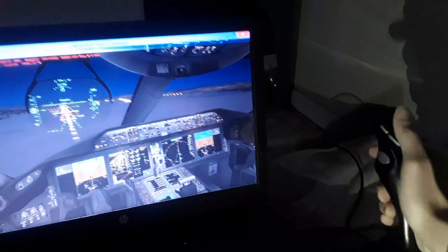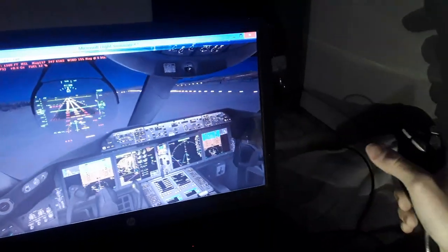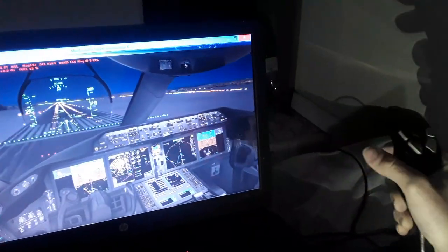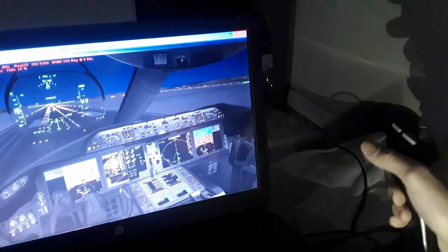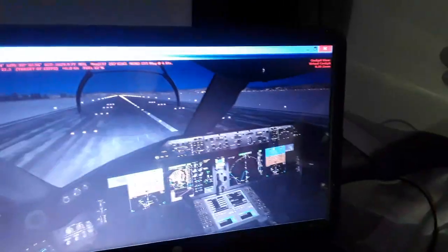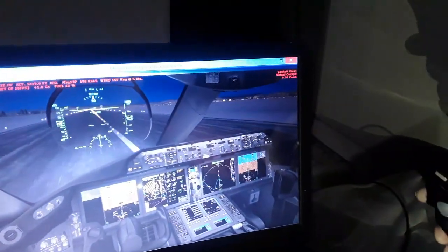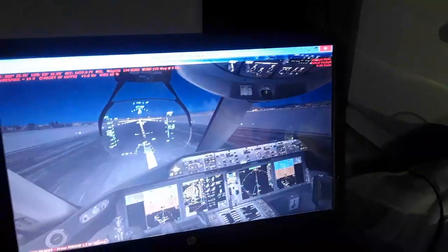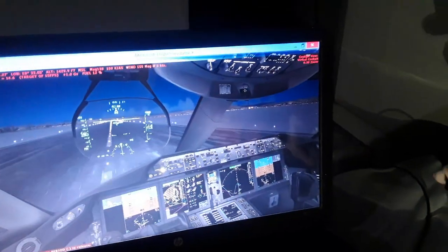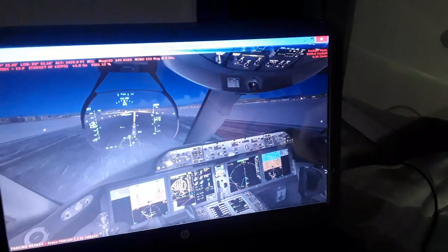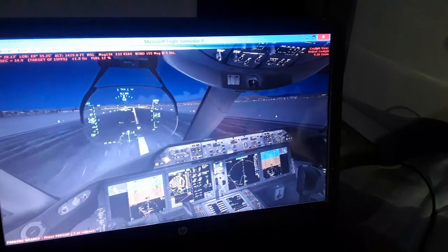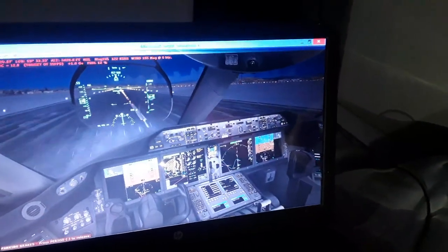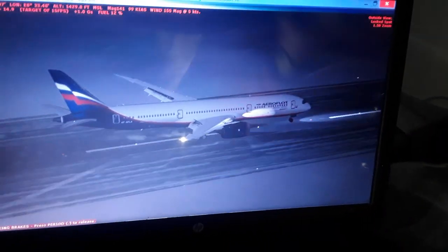We have the flare over here, gonna flare the aircraft for the touchdown. As you can see, beautiful touchdown here. Touchdown, parking brakes, and thrust reverse. So ease to idle and thrust reverser over here, as you can see, to stop the aircraft. So align with the rudder pedals as we're slowing down. So you can see we're slowing down the aircraft.